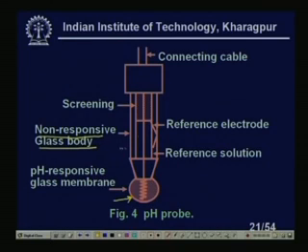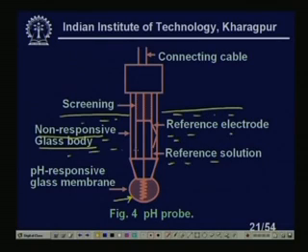So, there is no interaction. Even if we have a liquid up to this level, suppose in a beaker we put this electrode, what will happen is that this part will not act, but this is the pH sensitive glass. You see this glass is pH sensitive. It will react with the liquid outside, because it is filled with the reference solution. So I will get the measurements.